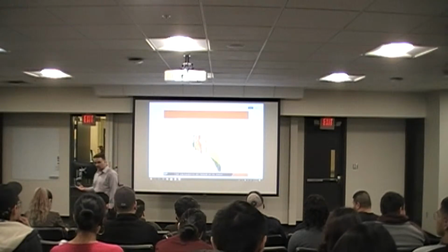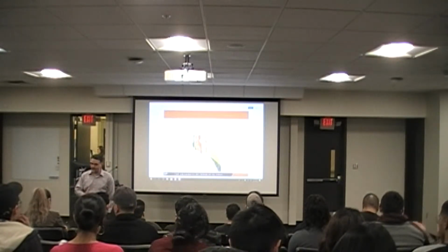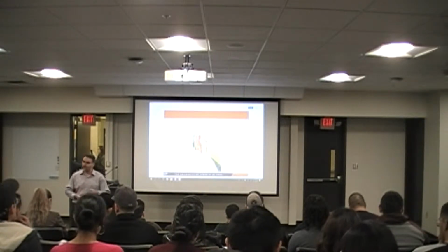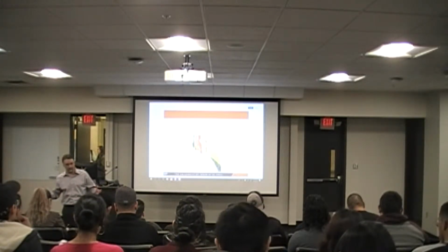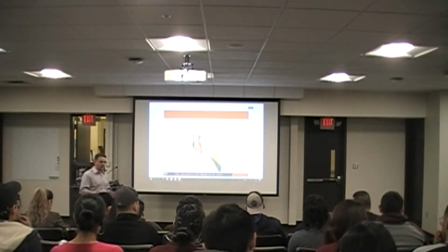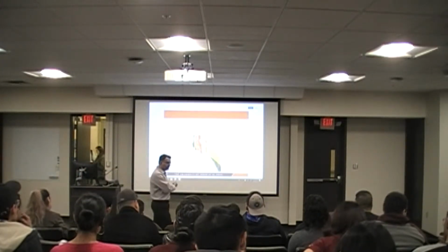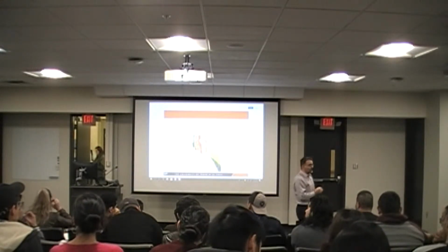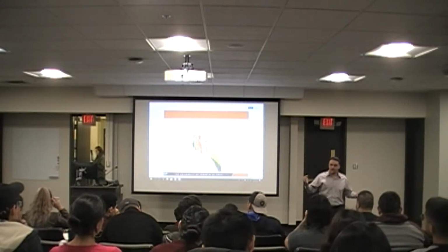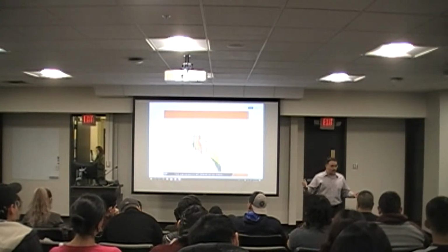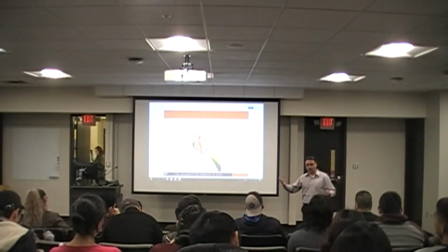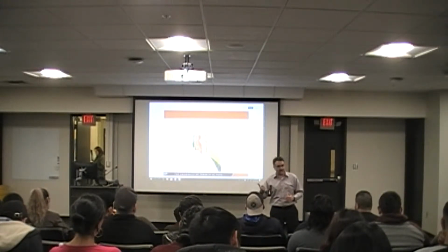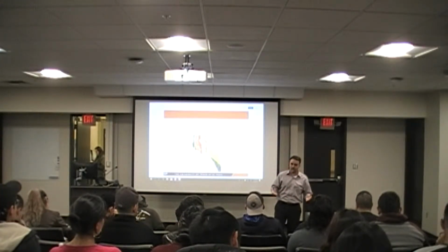And today we're going to talk about the simultaneous constraint that you have to satisfy to be able to classify your soil as well-graded or poorly graded. Right? We had the definitions before. Up until this point, we talked about the shape of the gradation distributions. We talked about we were interested in elongated S-curve because it has small, intermediate, larger particles. You can fit more material per unit volume. You can maximize the density, therefore you have better stiffness properties, right?